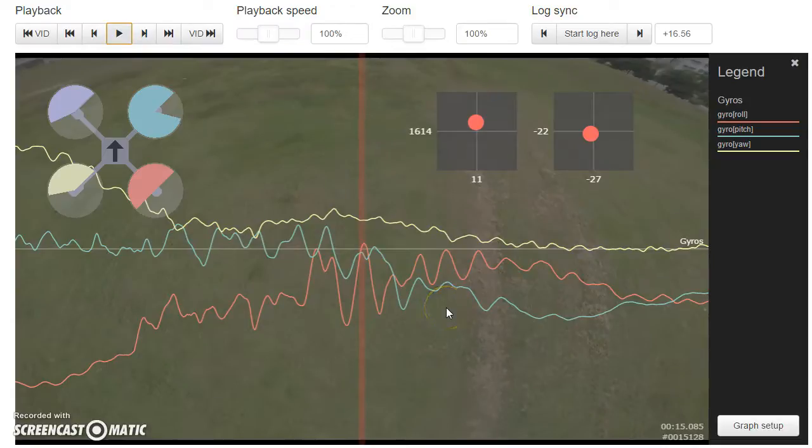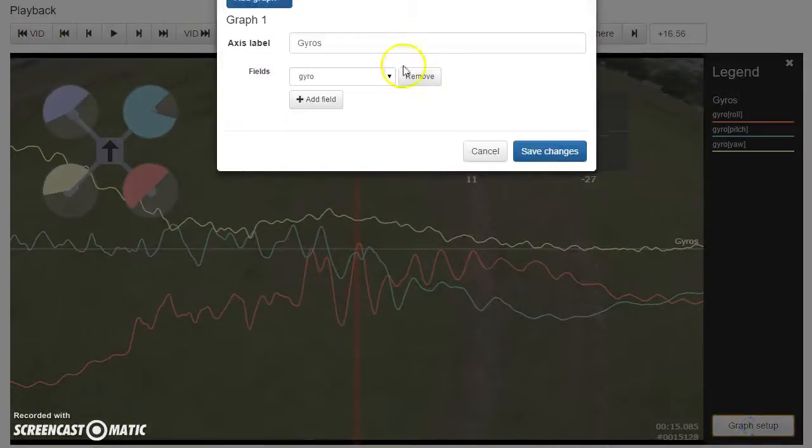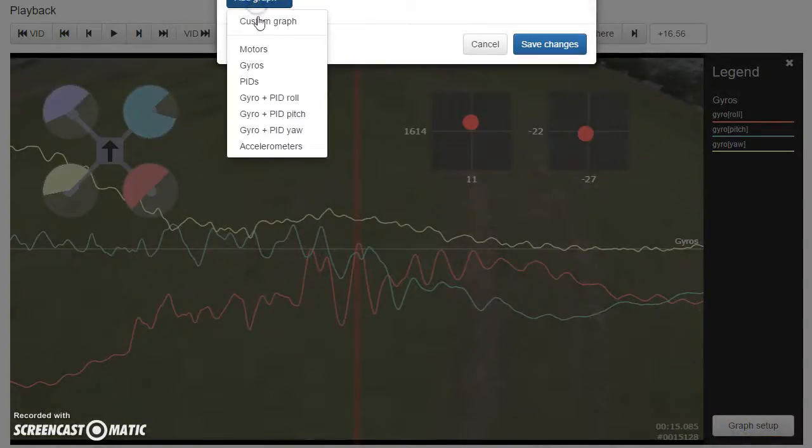It's very common to see on a mini quad that we get far more oscillation on roll than on pitch, and that's because of the weight distribution of the copter. The weight is more spread out on the pitch, front to back, and it is more centralized side to side. So the copter has less inherent dampening on the roll axis than on the pitch axis. So let's look at the roll axis first, since that's where this tends to be the worst.